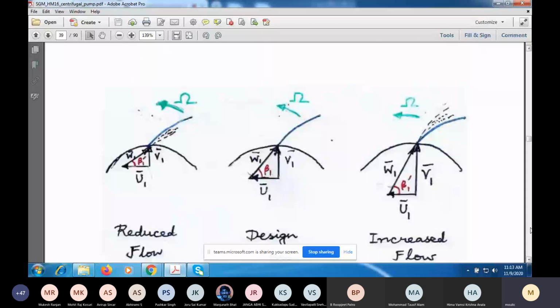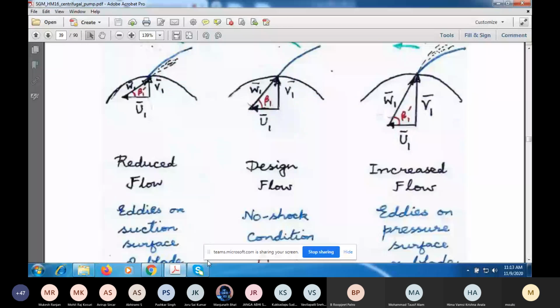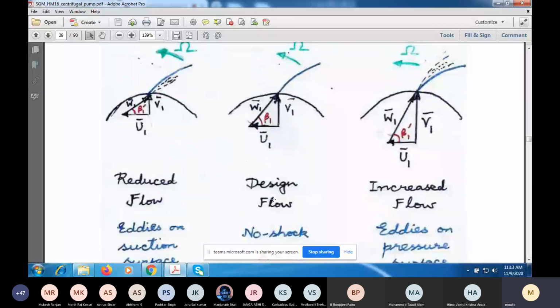So this I have touched on last time. In an inviscid flow model, there is no swirl in the pipe and no swirl in the impeller until it reaches the start of the region where you have blades. So the absolute velocity direction will be radial. So I've drawn the velocity triangle at a point where the radial line is vertical. So the absolute velocity is vertical here.